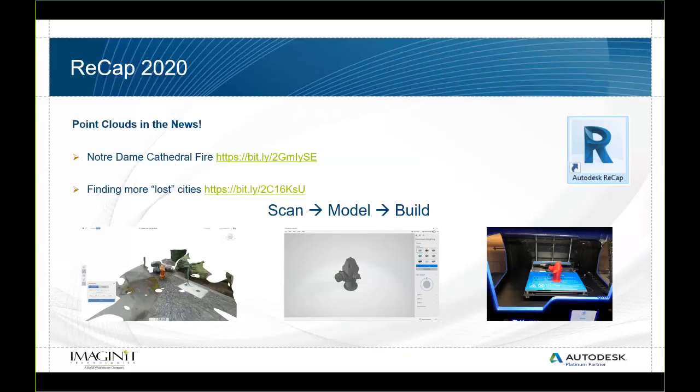I went out and took some pictures of a fire hydrant that was a custom fire hydrant for the county and the area that I live in. I did that with Recap Photo, posted a bunch of photos in there, processed it through the Recap Photo desktop app, and cleaned it up a little bit. In the second model, I cleaned up all of the outsides and cut off the bottom where the riser was. I ended up with just a standard fire hydrant, but it's that custom shape that we have here in the county. I exported that out to an STL file, and then I was able to 3D print it. I've got a small 3-inch-high 3D printed custom fire hydrant sitting on my desk, but that gives you an idea of the possibilities that are out there.